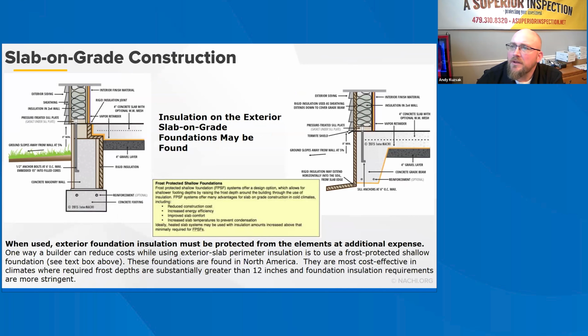All right. Slab on grade construction, concrete will crack as a normal outcome of the curing process. Cracking can be worsened if uneven bearing conditions, such as uncompacted fill areas, exist under the slab. The use of welded wire fabric reinforcement provides a means of controlling the severity of the cracking. And while fiber reinforced concrete may also provide adequate crack control, the introduction of fibers may tend to decrease the